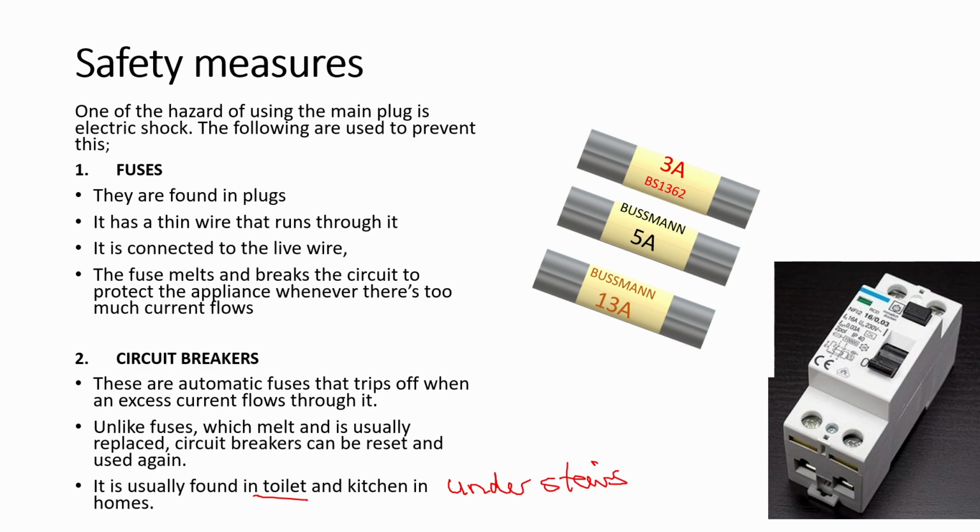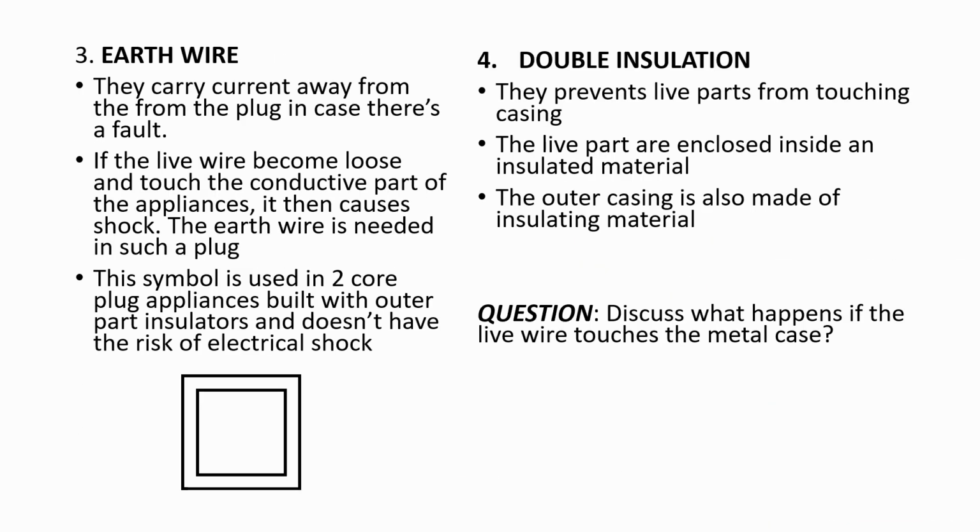Again, depends on the age of your house, but quite often there's a cupboard under the stairs and quite often they're put there. Yeah, very nice. And you've mentioned metal here. It's really worth just emphasising the fact that plastic appliances in the UK don't have to have an earth wire, but metal ones must.